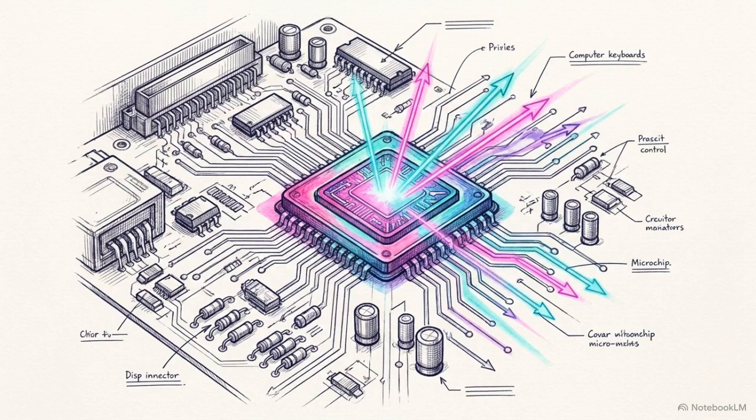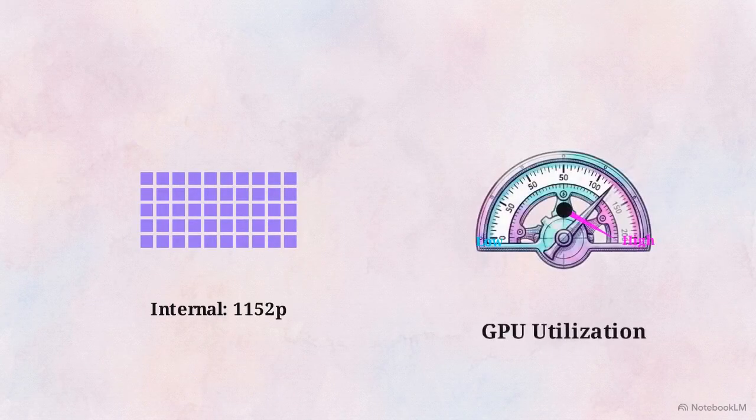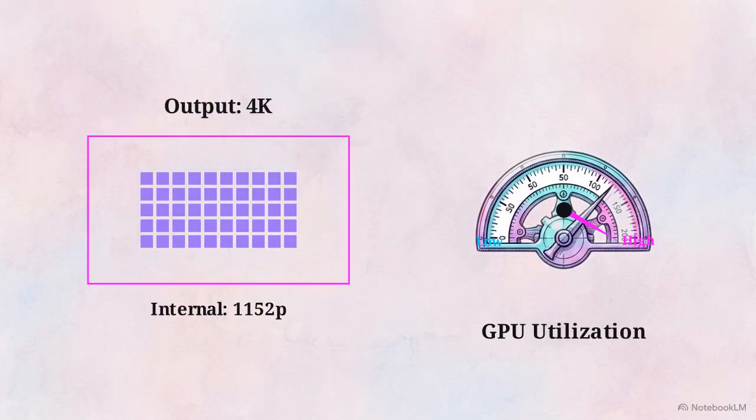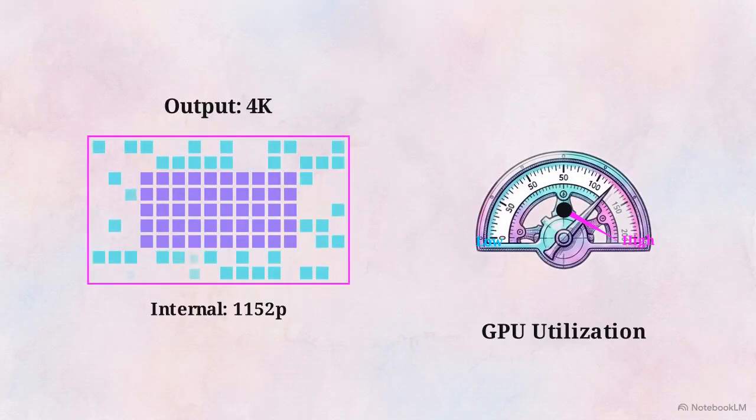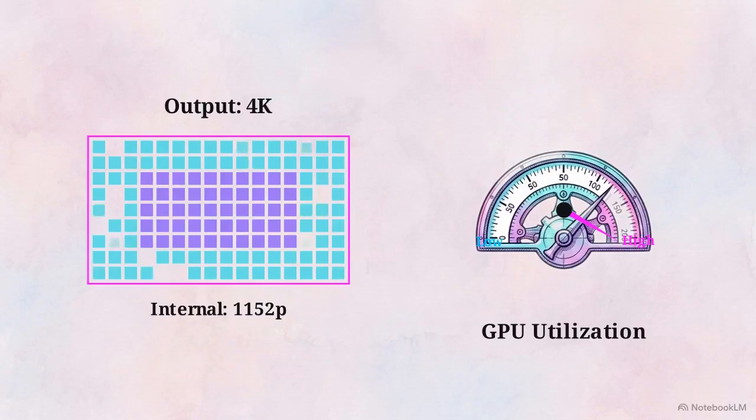To manage this heavy lighting load, developers use specific engineering workarounds to reclaim power for the graphics unit. This grid represents the native 2560 by 1152 array. The engine processes fewer pixels than native 4K, then uses temporal injection algorithms to computationally fill missing data until reaching a 4K matrix.